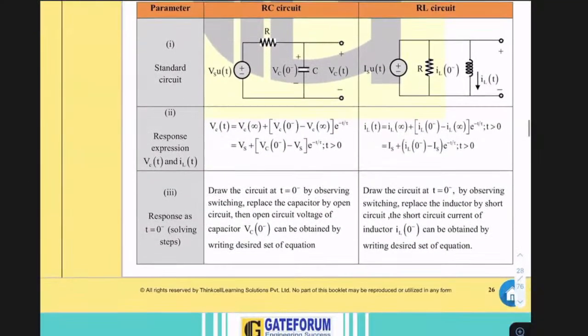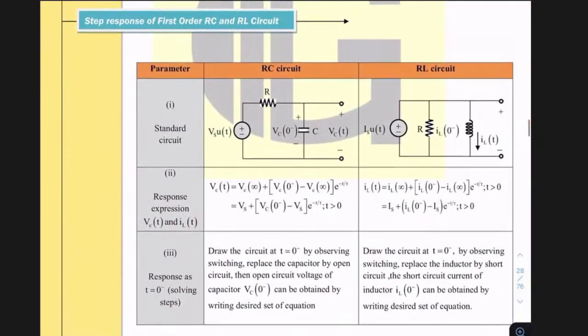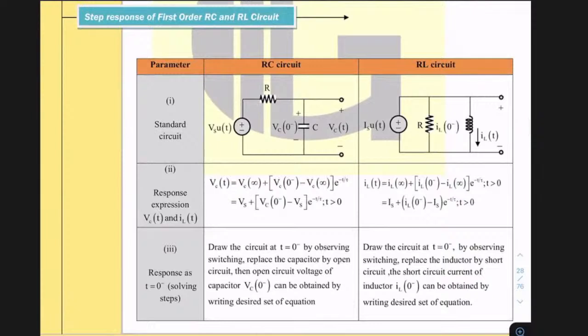Generally, there are two kinds of things you'll be encountering. Most of the cases you'll be getting questions based on first order circuits. First order circuit means the network will contain either one energy storing element, that is L or C. So you have circuits with L along with resistors, or circuits with C along with resistors.